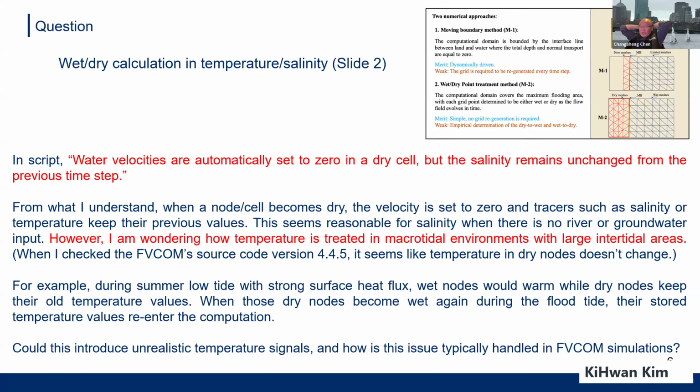I really encourage you, if you can, use satellite data. Remember, we used satellite data to determine the Changjiang River erosion stress. All the sediment models use the erosion coefficient, the stress, as a constant number. However, if you go to the Changjiang River, you find this erosion is very different from region to region. So we used the stationary satellite data from South Korea. With the South Korea stationary satellite, you can get the sediment image every 6 hours.